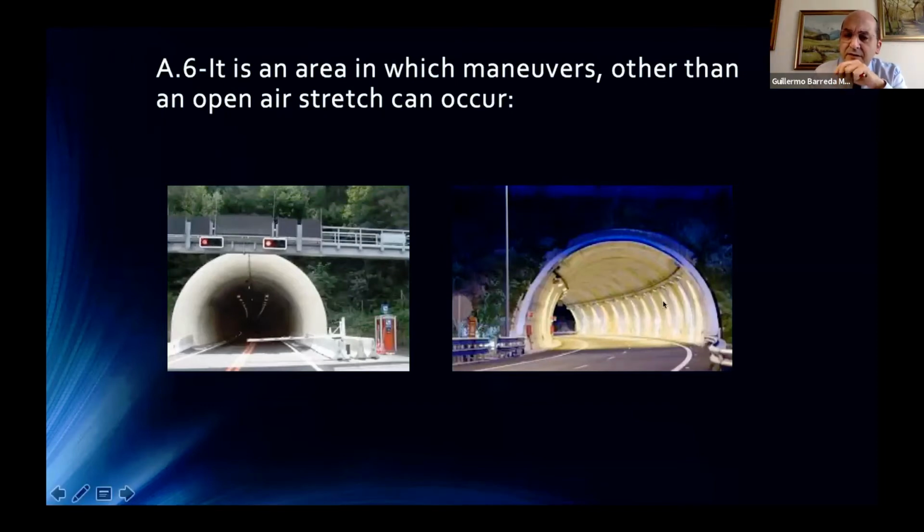We can see here that there is a huge intensity of light. So, well, it could affect the drivers by glaring them in this road. Moreover, we can see here that there is a mistake in the steel barrier. There are two noses here oriented to the traffic. Well, that is another point to consider when doing the road safety audit in this tunnel.